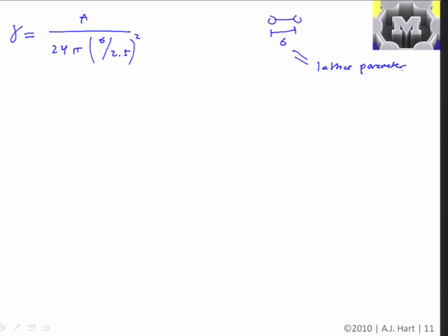So we're assuming we have a lattice defined by one lattice parameter, but the reading goes on to discuss that this is a pretty good approximation for most solids except for metals, and says that you can relate the Hamaker constant to the surface energy by this relationship and get pretty accurate results within 10 or 20%. The main exception to this is the case of metals, because metals have more free electrons, and because of the way they're bonded, the surface energies of metals are typically higher than they are in the case of solids where we're only assuming this van der Waals attraction.